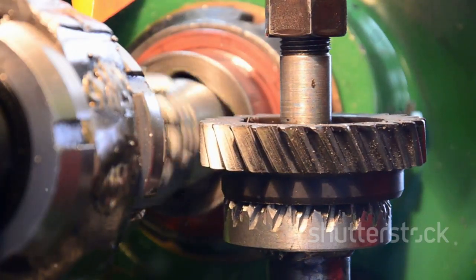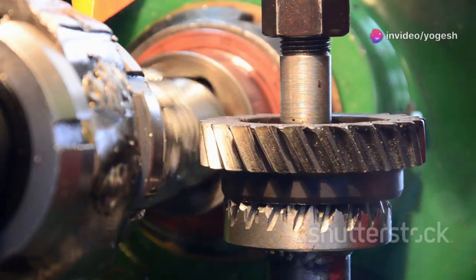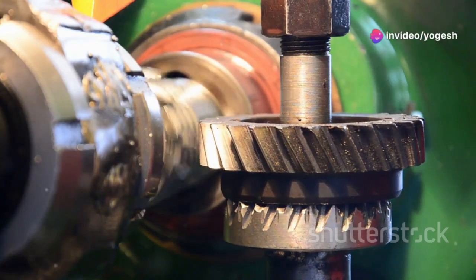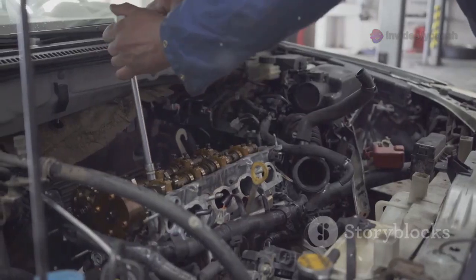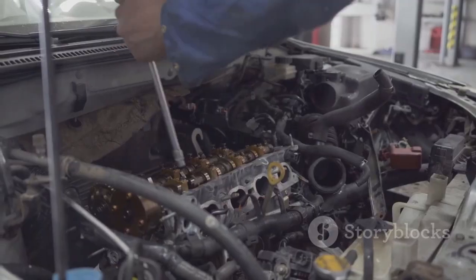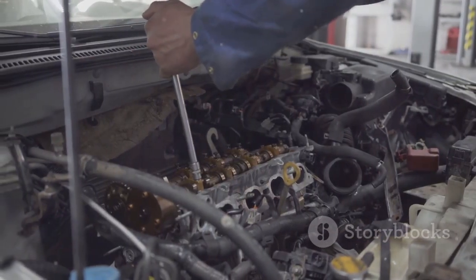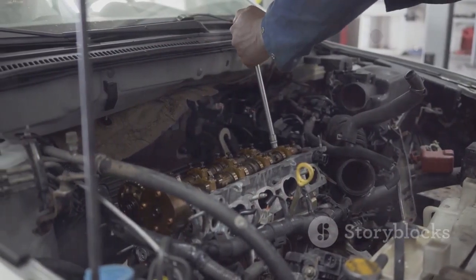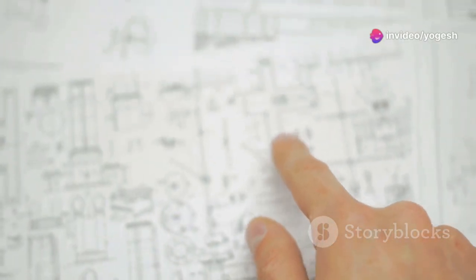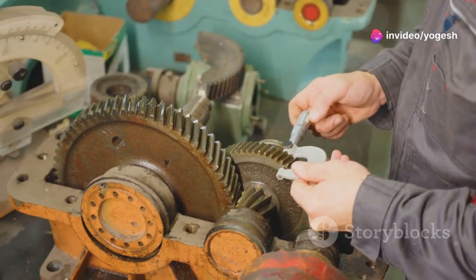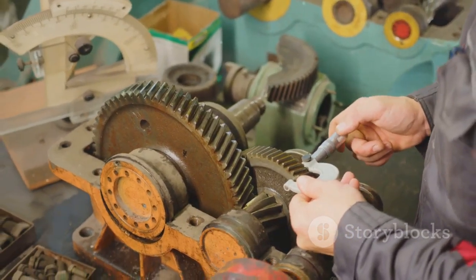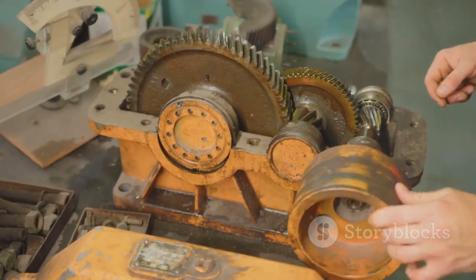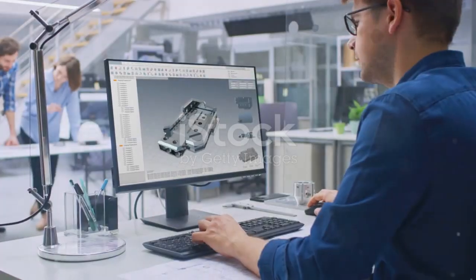Stage 3. Insert shaft sub-assemblies into the housing, ensuring proper gear mesh, confirmed by a sectional view. Final stages. Apply sealant to the cover, assemble with bolts, and torque to specification. Each step is visually and textually reinforced, preventing common errors. This multifaceted guide ensures the gearbox is assembled right the first time. The result, a reliable, high-quality product.